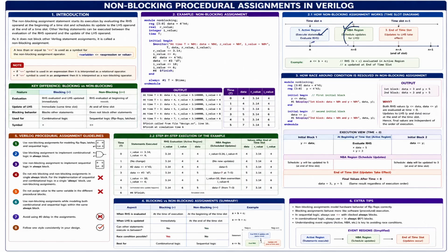See, the non-blocking region executes in the middle. After execution of the active region, we go to the NBA region, non-blocking assignments. In the active region, blocking statements are executed first, and then $display statements are executed next. Then, in the active region, the right-hand side of the non-blocking statements is executed next. I will explain these regions later, clearly. We have four regions in our Verilog: the active region, non-blocking region, inactive region, and postponed region, which includes the monitor region.